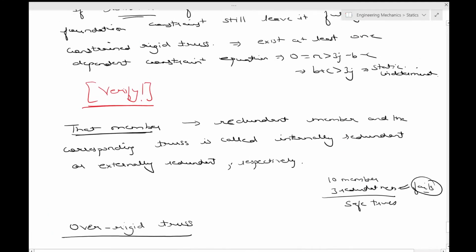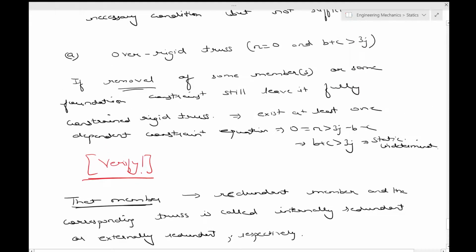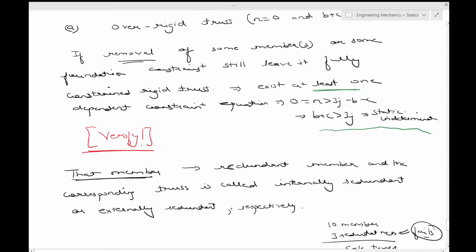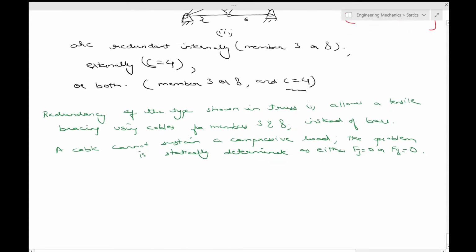At least one dependent equation, that one gap, is now filled. This was causing static indeterminacy, and now if a cable is put in, then it becomes statically determinate.